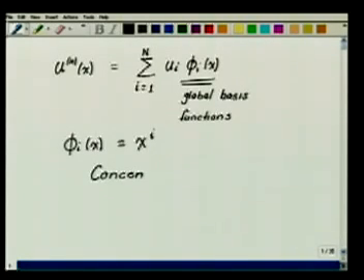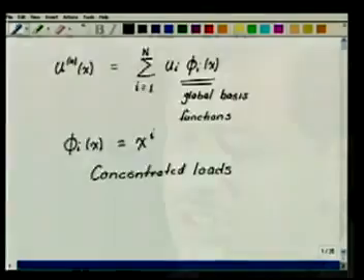In fact, they did a very bad job of approximating the derivatives, which are of prime interest for an engineer. So we said that fine, these phi's fail for this set of problems where concentrated loads are applied or when we have material interfaces, which are of practical interest to an engineer.